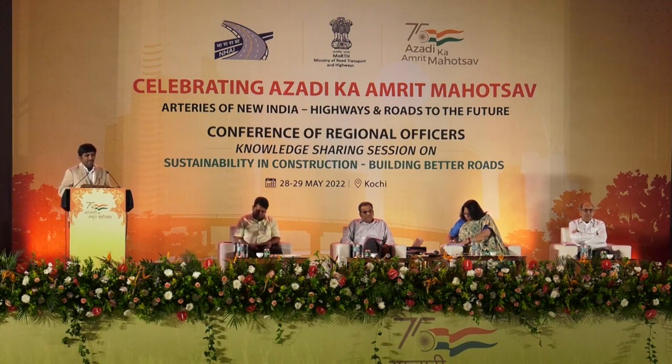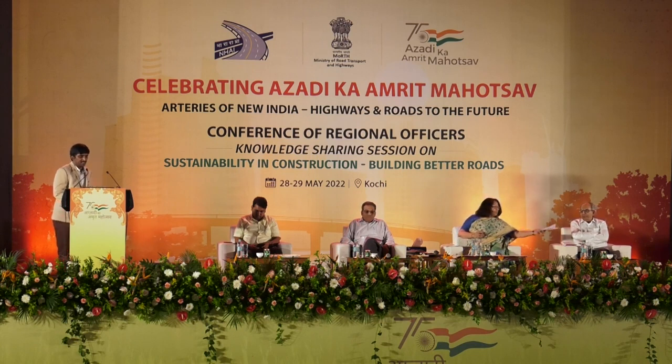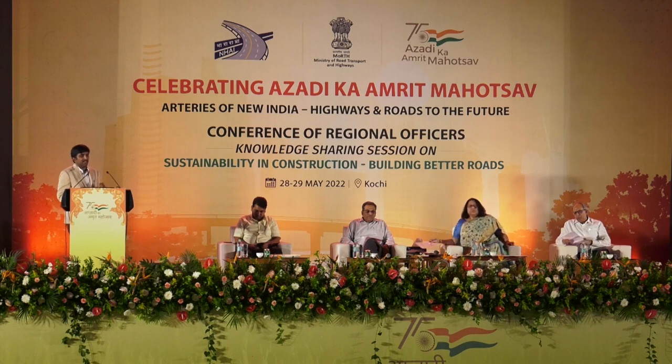Basically, the advantages are that it conserves energy, it conserves materials, it is long-term cost effective, environmentally desirable, and maintenance cost will reduce significantly. So the main takeaway is, whenever you find a distressed pavement, first you have to investigate. If your distress is in the base or sub-base layers, FDR is the most suitable option. In that case, the same material you can reuse. Above that, very thin asphalt layers are sufficient.